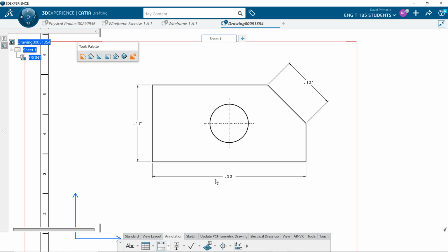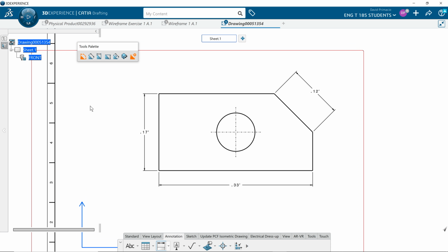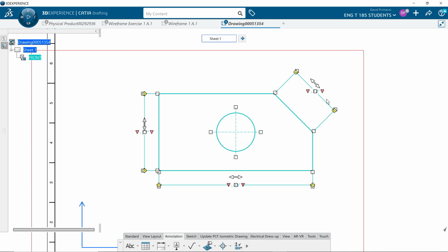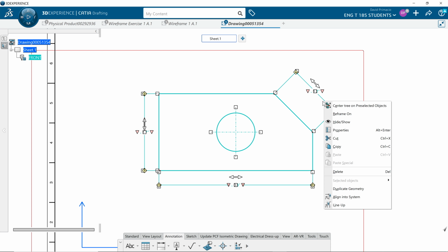The default is to be in feet and inches. You can highlight all your dimensions and convert them to something else. I have to turn off the dimension feature, highlight all dimensions, right click on one of the lines of the dimensions and go to properties.